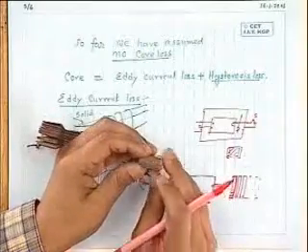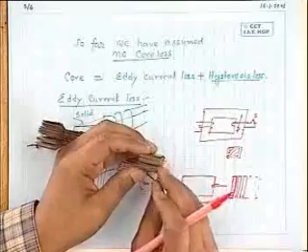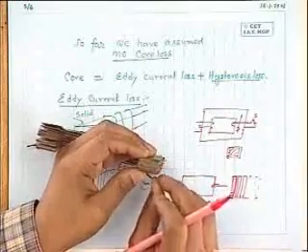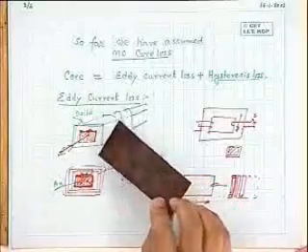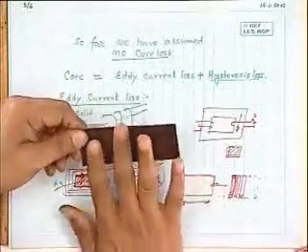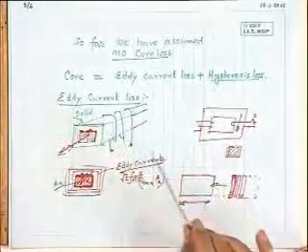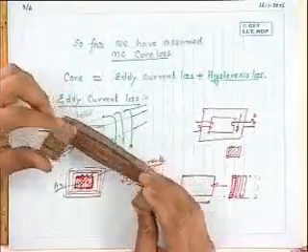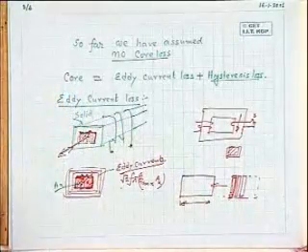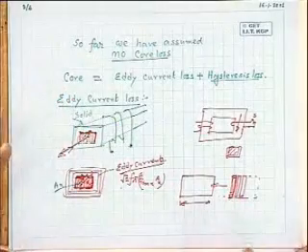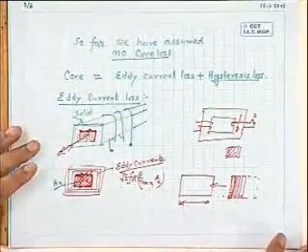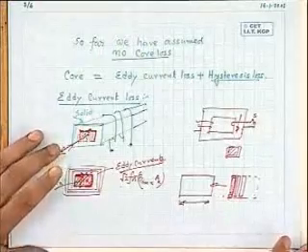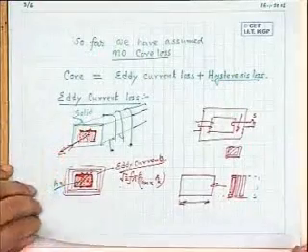What I am trying to tell is that each plate should be insulated from the other plates. Generally, they are given a varnish coating to insulate them from one another. The color of such plates will be like this. It is an iron plate, some varnish coating is put, and they are stacked together. The important point is that the plate should be made thinner. There is no other way out, otherwise there will be a tremendous heating effect inside the core of the transformer.